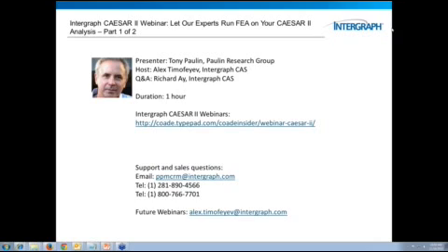Okay, let's see, this is from Dave. Several questions. We're expecting FEA tools to evaluate components. Can you state that the tool is mainly for modeling components more accurately instead? Okay, yeah, FEA tools does have a component modeler in it, and the components that it models are bends with stanchions, bends with steel. It models pressure vessel heads with nozzles, pressure vessel heads with offset nozzles, vessels with hillside nozzles. So those components it evaluates.